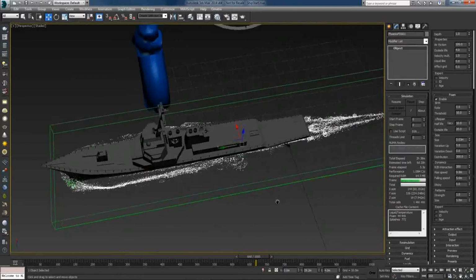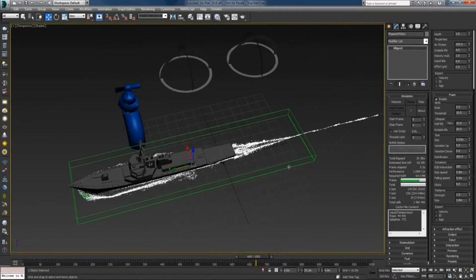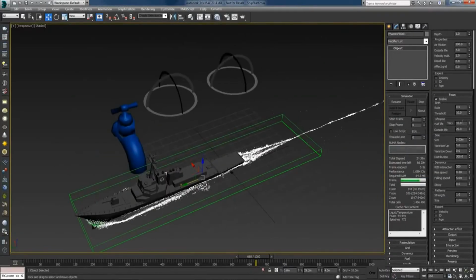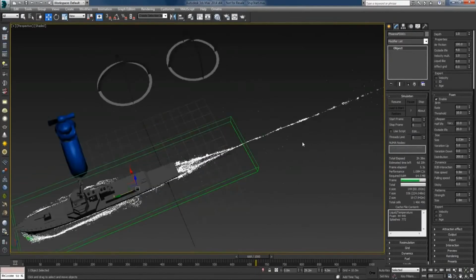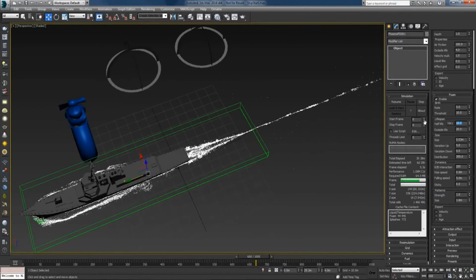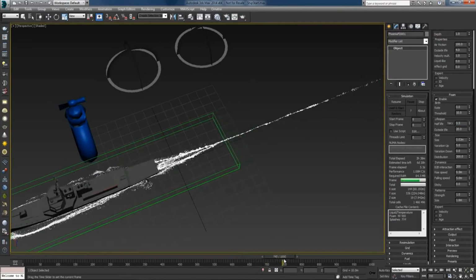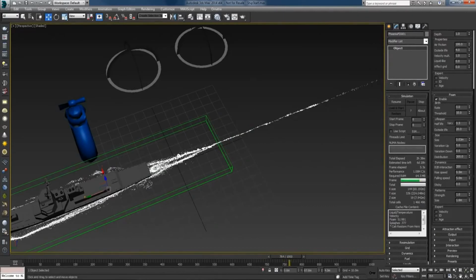And for now, I think I can decrease the half-life, because right now the foam seems to live forever. And I will set this to 0.5 and find the frame where I can restore. Okay, so here is a frame that you can restore the simulation. So I'll hit stop and restore with the new half-life, and see how this will affect the whole thing.